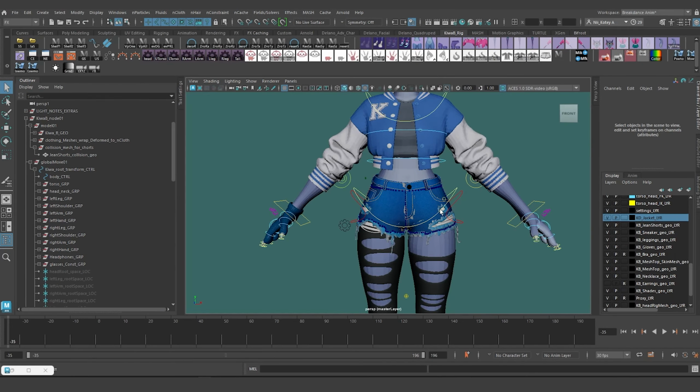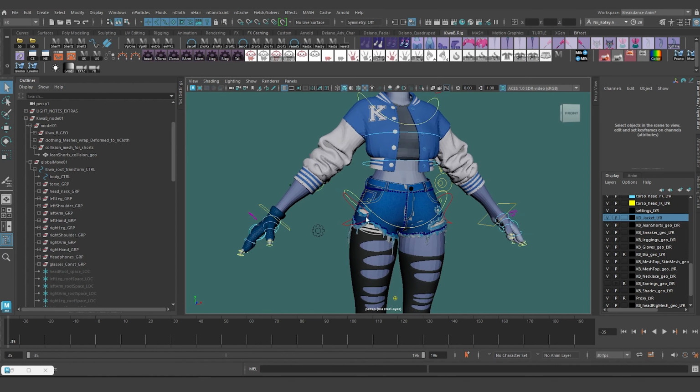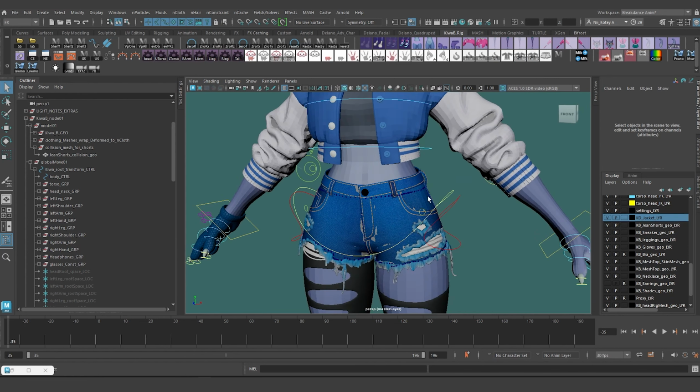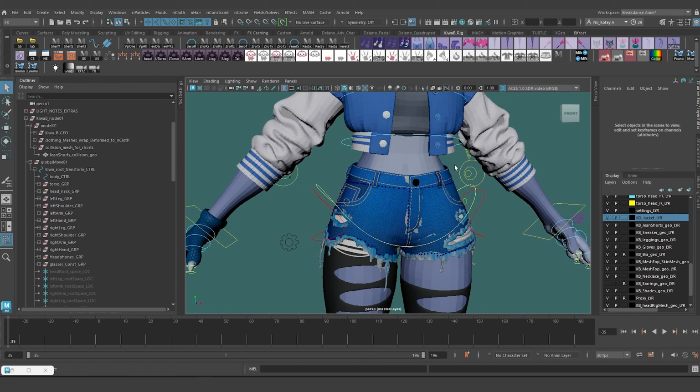The next thing I'm going to work on is a set of custom attributes to toggle my simulation meshes and their wrap deformer envelopes. As I mentioned before, wrap deformers are very expensive, and when I start simulating nCloth for my new animation, I don't want these wrap deform relationships to be simulating. I want to be able to just watch the simulation mesh and analyze it and make sure it's simulating properly. And then when everything is working and I'm ready to cache, as I did in this course, I'll turn these meshes on and turn on their wrap deformer relationships to the simulation mesh.